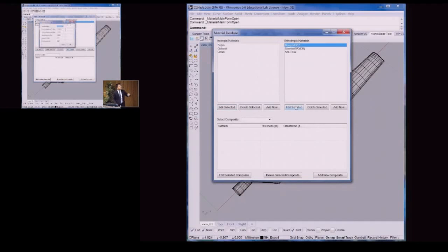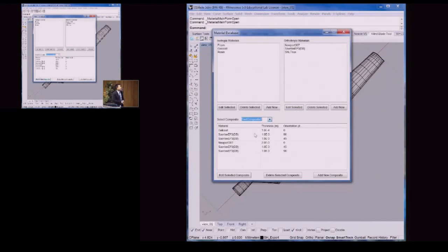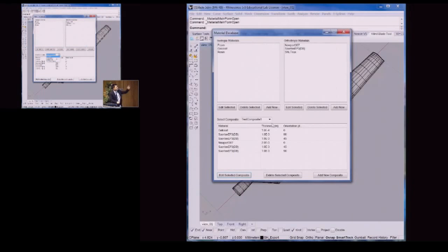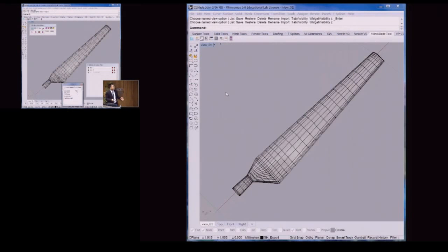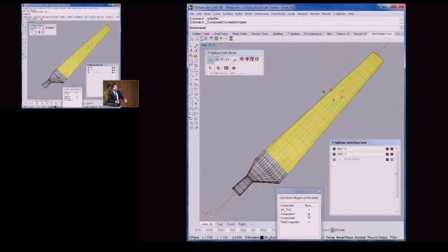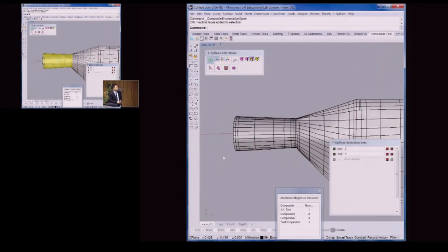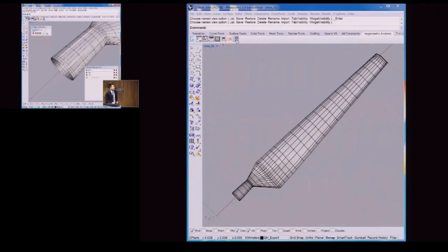In this tool, we can also give isotropic material on the left and isotropic material on the right, and then you can specify different layers of your composite material. You can give very different properties and then lay it up. Everything, again, is through parameters. Using these parameters, you have the design of the material. Then you can easily select different zones and assign the composite material you just specified. Everything is still under one same framework. We didn't switch between different softwares.